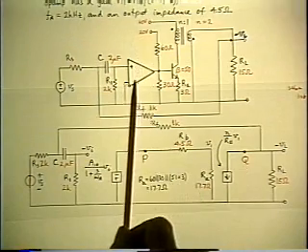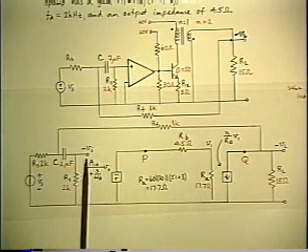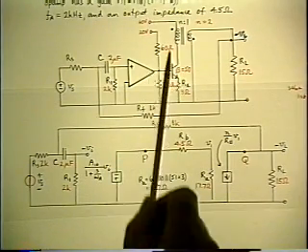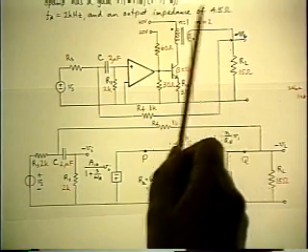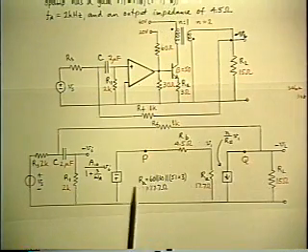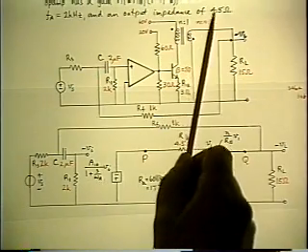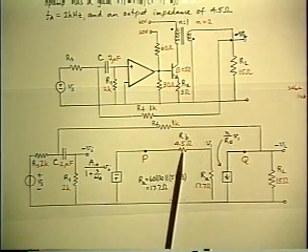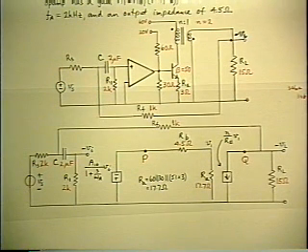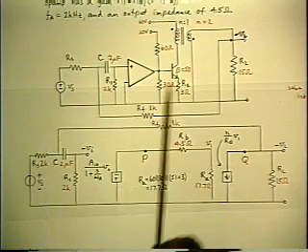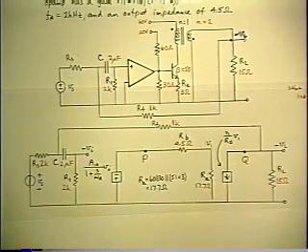Likewise, all you need to represent the driver stage is infinite input impedance with the voltage VI, represent the output by a Thevenin generator described by the specification, which is a flat gain of 8 dB, a pole at 2 kilohertz, and an output impedance of 4.5 ohms, which is the RB. So that takes care of the forward path, and the rest of it remains explicit as it is in the original picture.